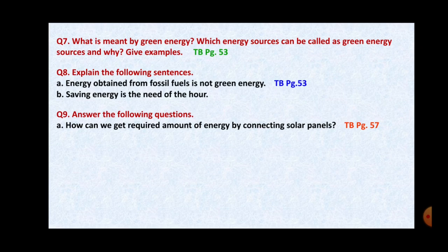I am just giving you the important points which you will write and you will elaborate. Now first you will write that the photovoltaic solar cells can be connected in series or in parallel to make a solar panel, right? Then the second point you can write, the current generated from the combination is equal to the current from an individual cell. It means that when solar cells are connected in series, currents from the individual cells are not added, right?